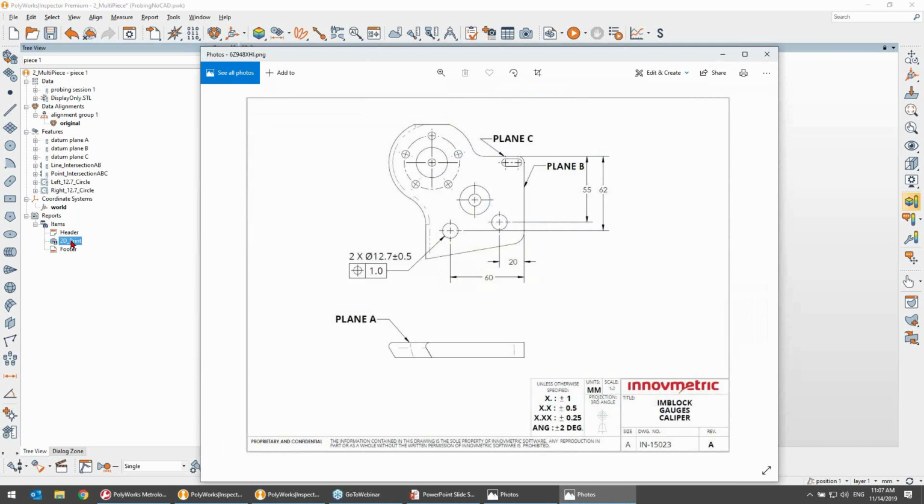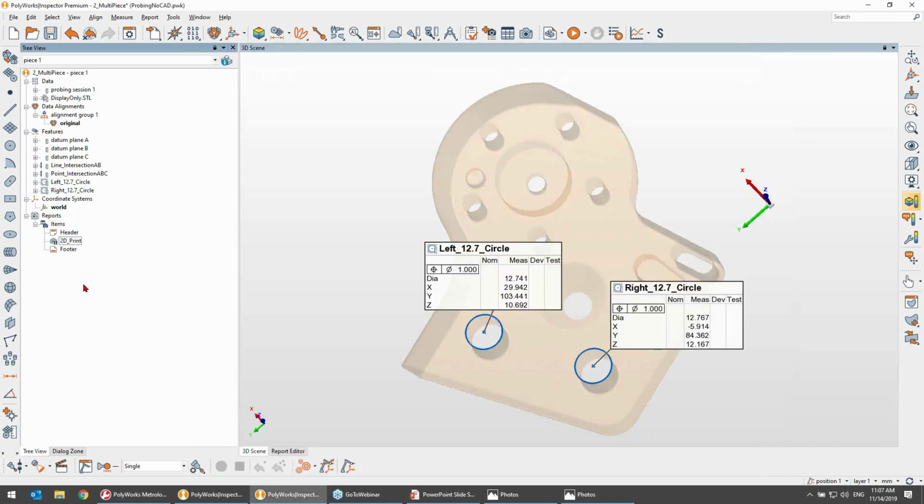Those of you familiar with the typical CAD inspection workflow know that it's a good idea to align your device to the CAD model as soon as possible. This is still the case when no CAD model is available, since being aligned to your nominals allows you to use guided probing, see if you're probing the right object at the right time, and when no CAD model exists, this is also required to be able to create distances and nominal primitives using the right coordinate axis.